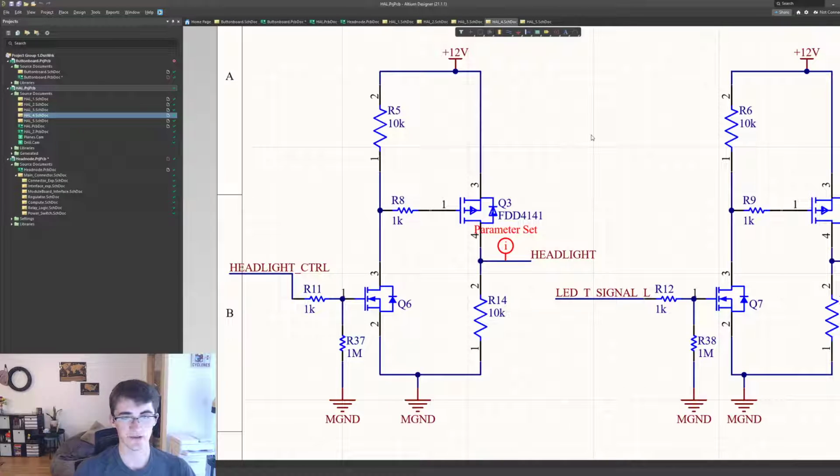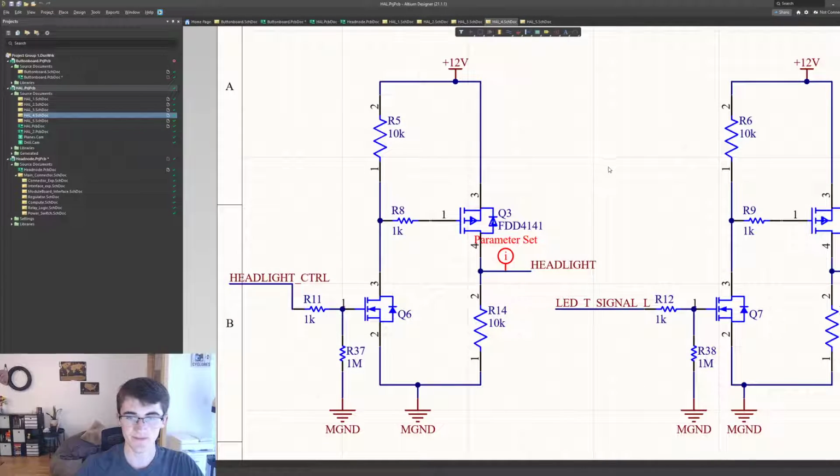This actually had a really interesting application at race, because our horn broke because we were using it so much when we were passing people on the track. We had to go run to the shop and get a new horn, and we didn't know how much current it was going to draw. But this spec handled up to 10 amps instead of only 2 or 3 like it uses. So we were able to swap a new one in just like that and not worry about it.